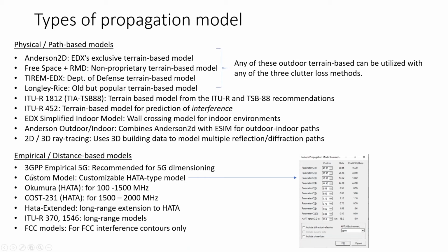But it's important to understand that these models, while they may be recommended for certain applications, are only going to be a rough estimate of propagation distances. So for example, if I use the Okamura-Hata type model, I may not see critical shadowing due to terrain. If my base station is right next to a big hill that's much taller than the base station, the Okamura-Hata model is not going to extract the terrain along that path, and it will not see that hill.